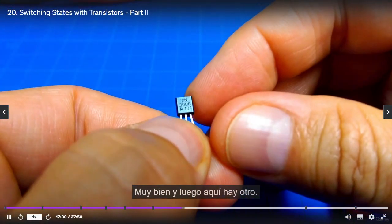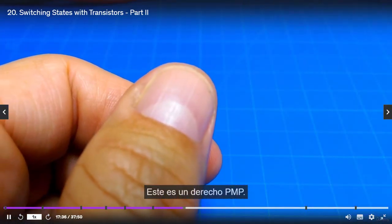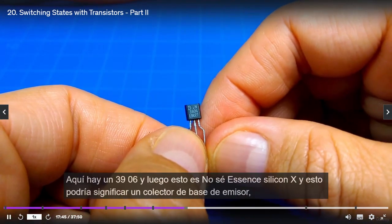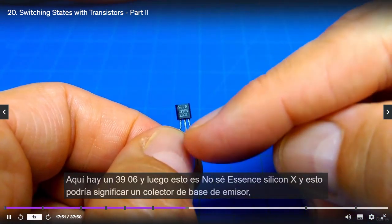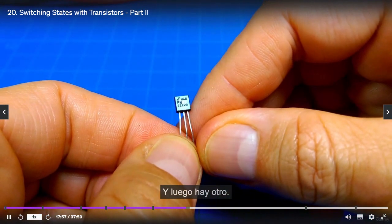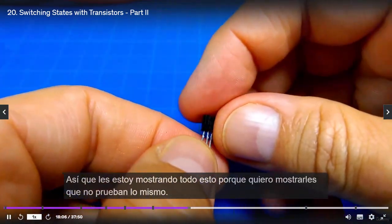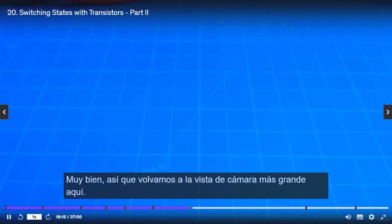All right, and then here's another one, a 2N3906. See that little M on the bottom left? That's a Motorola. This is a PNP. And then here's another 2222A. This is a Fairchild part, another NPN. And then what's this one? Here's a 3906, and this is, I don't know, Siliconix. This might mean emitter, base, collector, but you never know. And here's another one, another PNP. I'm showing you all these because I want to show you that they do not test the same. So let's go back over to the larger camera view.